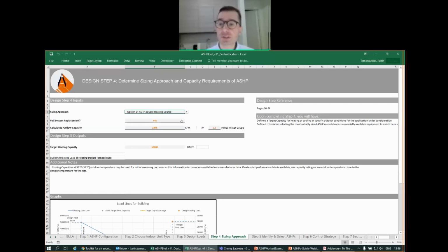So there's certain regions in Canada that you're going to have design temperatures below minus 25, minus 30. And in those situations, you're really going to struggle to find an air source heat pump that's going to be able to meet the full heating loads of the building at those temperatures, or even really operate below minus 30. So those are some of the things to keep in mind when we're evaluating between option C and option D.